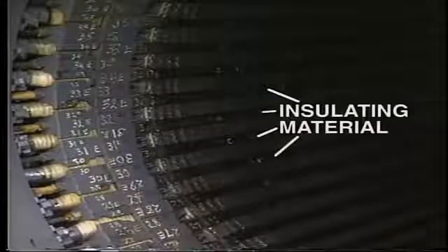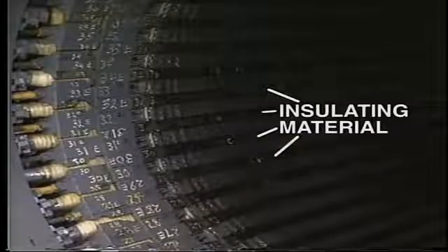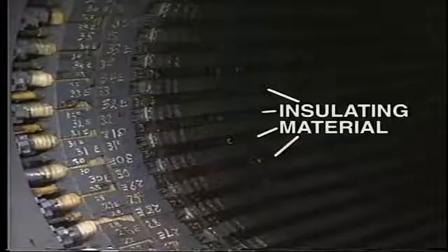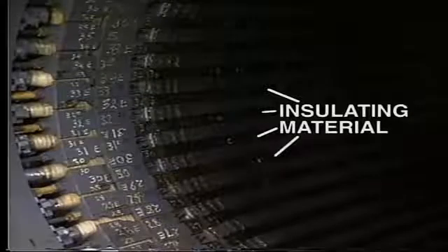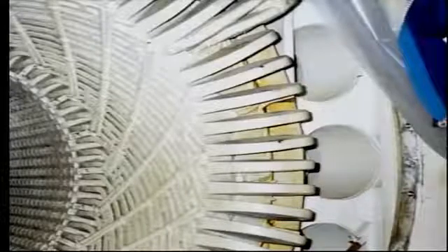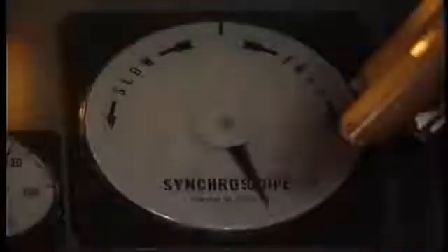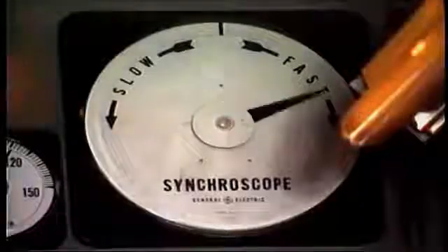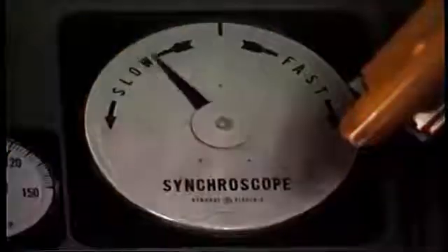Once the stator bars are fitted into the core slots, they are joined at the ends to form continuous coils or windings. These end connections are referred to as end turns. The conductors are securely held in the slots by wedges of insulating material. This is extremely important, as the windings are subject to quite heavy mechanical forces during operation. The windings may try to twist during heavy power surges or electrical faults on the power system. Similar distortion of the windings may occur if the generator is incorrectly synchronized, that is, connected to the system when it is out of phase with the system.